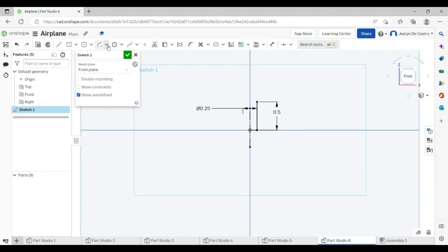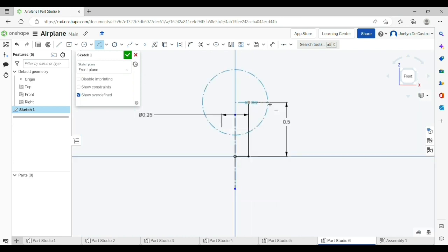Next, add the rounded head. In this, use a center point arc. Project over vertical coincident to the origin. Project it from the end of that line. That will be the center. Click out there and then vertical with the origin here.